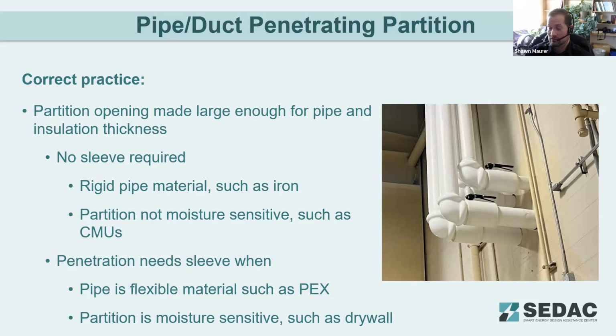And then if it is an exterior wall, for air barrier continuity of the building itself, you also need to seal the building penetration to that exterior jacketing of the pipe with some kind of foam material, caulking, adhesive tape, some kind of material that's going to cover that building penetration and seal it to the pipe penetration so you don't have an air leak there. That would be a detail that you would have to add in for those types of penetrations as well.